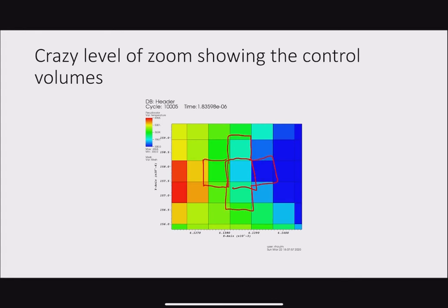And essentially what the code does is it computes the flux on this cell edge here, the flux on this cell edge here, the flux on this cell edge here, the flux on this cell edge here, and for conservation of mass, it just walks around the control volume and solves partial t, the integral over the control volume rho dV, plus the surface integral of rho v dot n hat dA is equal to 0.